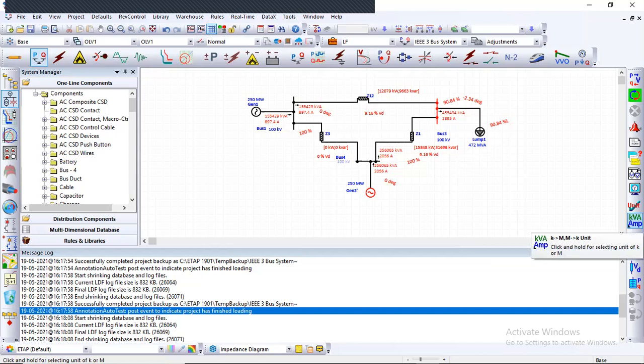After that, if you're not interested in seeing the ampere and kVA rating, you can click so that the kilowatt rating shows the real power from this side, and individual lines, buses, generators, and lump loads can be seen by this option.